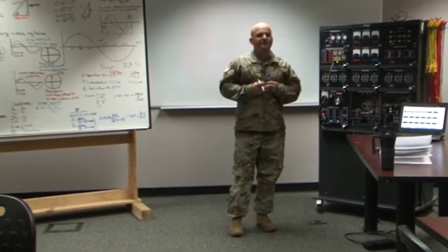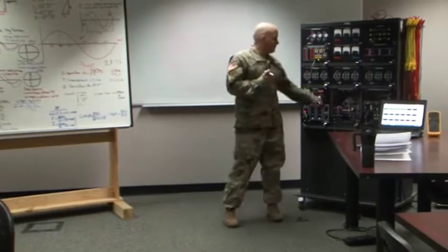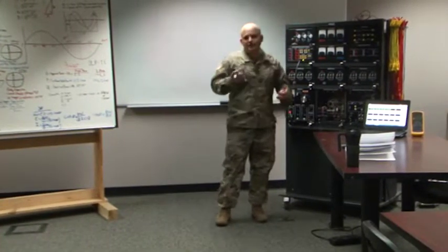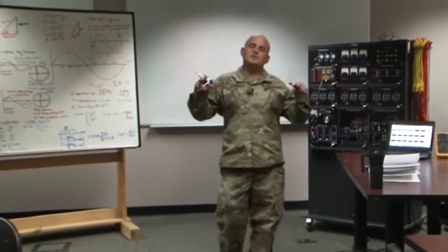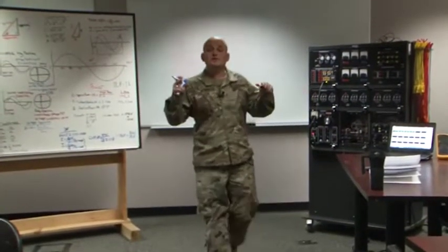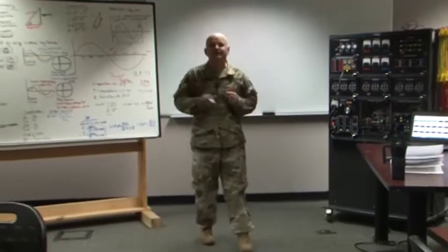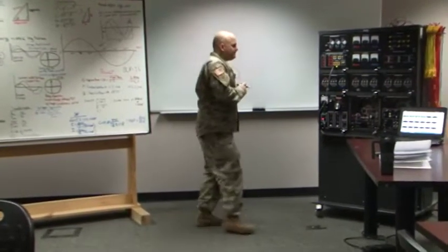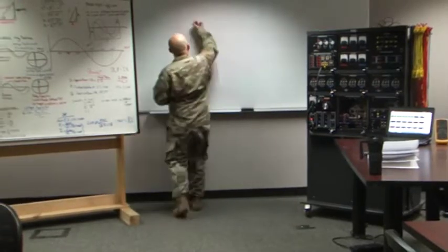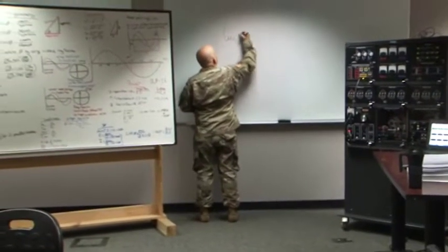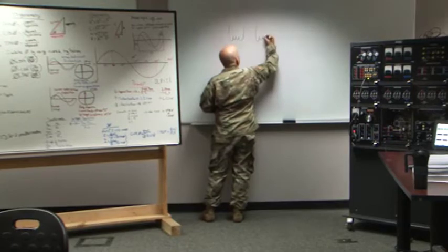We're going to be using the three-phase transformer block here, and that is going to be the principal source for this last day, and this is going to require three-phase power. So we're either going to be generating our own three-phase power from here, or depending on your class, the instructor may set up a common bus above you, and then you will just tap down from the common bus and get that three-phase. But one of the first things I want to talk about is, again, let's look at this like three separate single-phase transformers.